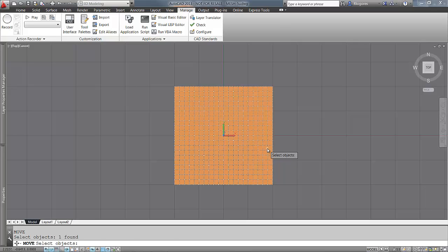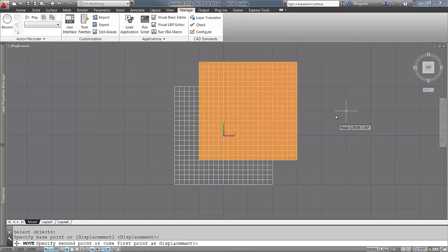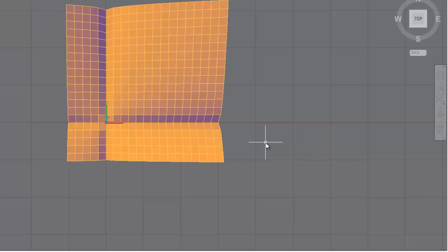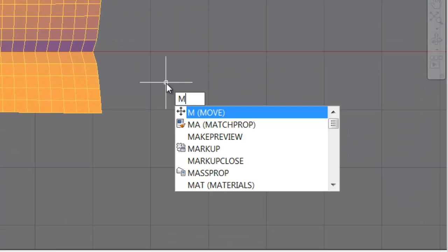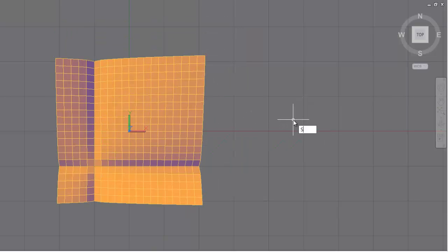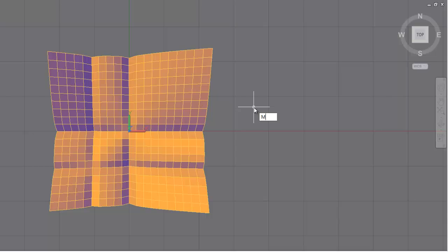Surface equations are always referenced to the coordinate system's origin. We can achieve a series of complex forms by changing the mesh object's position or rotating it. In the screen capture we are showing, the mesh is moved and the shaping command reapplied. Once we have achieved the desired shape, it will be smoothed and the thicken command used to transform it into a 3D solid.